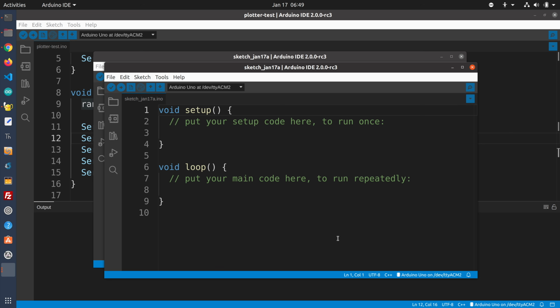Now, once again, I've discovered another bug in the Arduino IDE 2.0, and it again has to do with serial ports. And this one affects both the plotter and the serial monitor. Now, what I've done over here is I'm running the same sketch that we ran in the last demo just to show the plotter, but I've opened a number of other IDE windows, and I'm in a third window right now of my IDE. Now, I'm connected to my Arduino, and you can see that over here. So if I hit the serial monitor, I should be seeing the data, right?